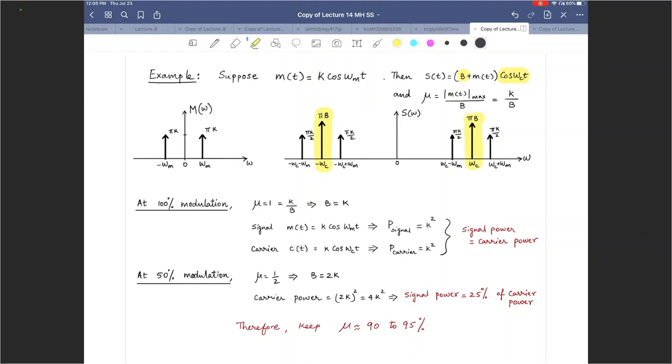That is what I meant by non-suppressed carrier. As you can see here, we are sending the carrier along with the message. So in asynchronous detection, because we are trying to track the envelope in almost a cheap manner, we will have to add the bias to the signal in order to do it properly. And if we add the bias to the signal, we will have the carrier being sent along with the message. So we are using the transmission power. Some of it is being associated with the carrier, some of it is being associated with the signal, which is the information, right? So I'm using that power budget that I have, some of it for the signal, but some of it for the carrier as well, which is not helping with the information. It's only helping with the detection.